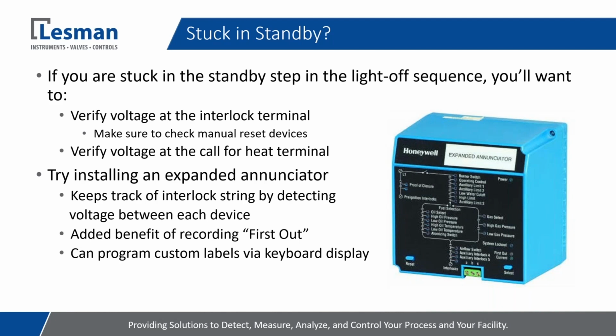And again, the most common one that I see in applications is the manual reset device, right? Like an excess temperature limit interlock or a low or high gas pressure switch, which has the manual reset. For a high temperature limit, once you go above the threshold, the temperature needs to go back below the threshold again, but it's not automatic reset.